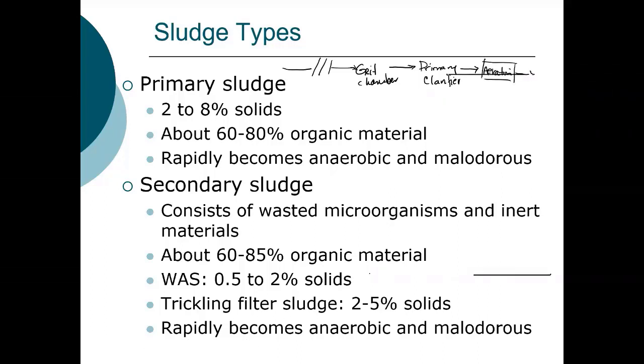From aeration, where does the water flow after the aeration tank? The secondary sedimentation or clarifier. And if you may recall, the return activated sludge is pumped back into the aeration tanks because these are the microorganisms. So secondary, and then we have waste activated sludge,